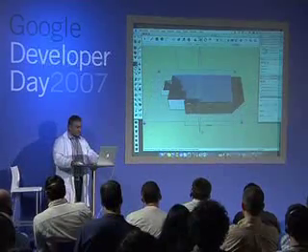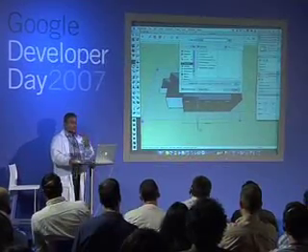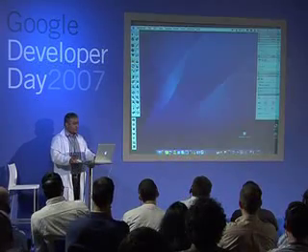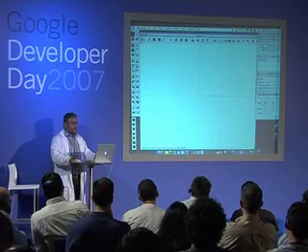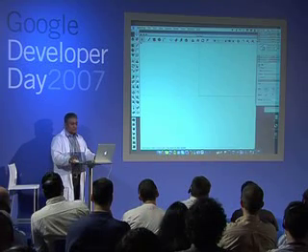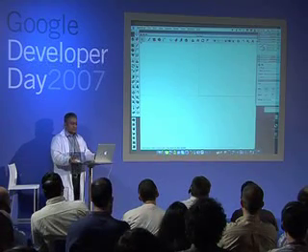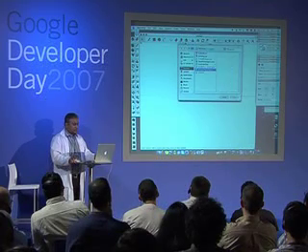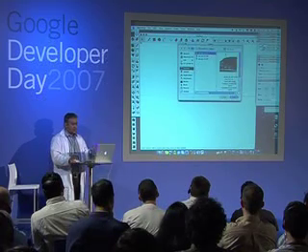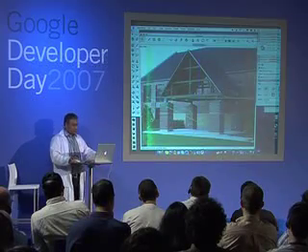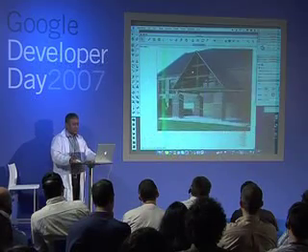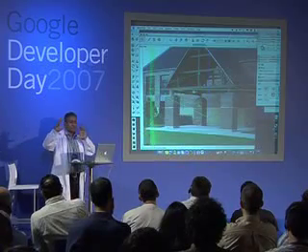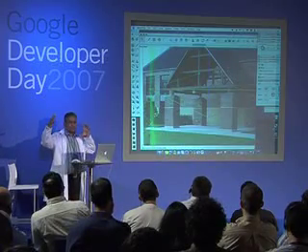Okay. So I will save this, and I'll show you how to now use pictures to actually make 3D very simply. Okay. So I will now just add one picture. We call it photo match. So I will choose a photo. So let's see. Okay, here is a simple photo. You see this grid appearing. Okay. We are now going to match the SketchUp environment to the same perspective of that